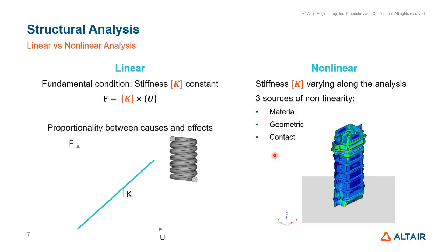You have this sliding contact that has some friction on it. This represents nonlinearities. And also whenever you're dealing with an open gap, what I mean about that is you have two components which don't touch each other, neither virtually nor physically, and when you start pushing one to another, they will get into contact, and this will increase the stiffness of your system, and this is also one of the causes of nonlinearities.